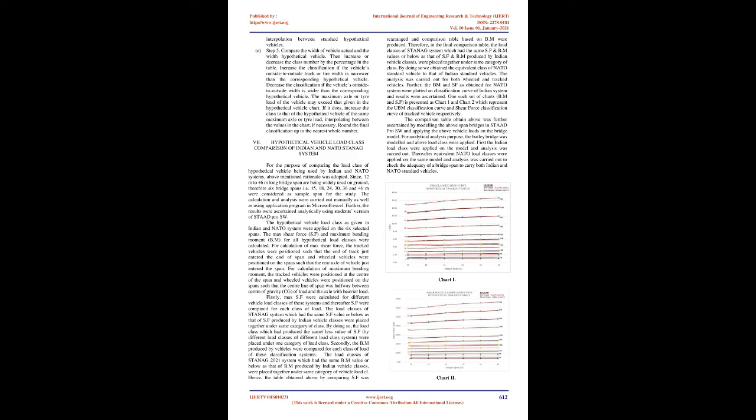6. Analytical vehicle classification procedure. Standard vehicles are normally classified using the analytical method. To classify a vehicle using the analytical method, the following dimensional and weight distribution data are needed. A. Gross vehicular weight, empty and loaded. B. Load on each axle, empty and loaded.